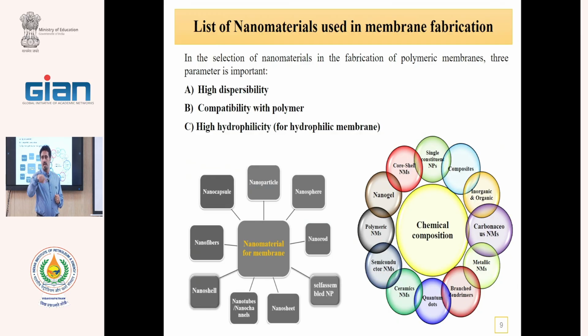For this, we can use high-rate mixing, where the nanoparticles contact each other and can separate. But the easy method is using ultrasonic, where the produced bubbles can knock the particles and cause dispersion. This dispersibility is an interaction between nanoparticle and solvent.